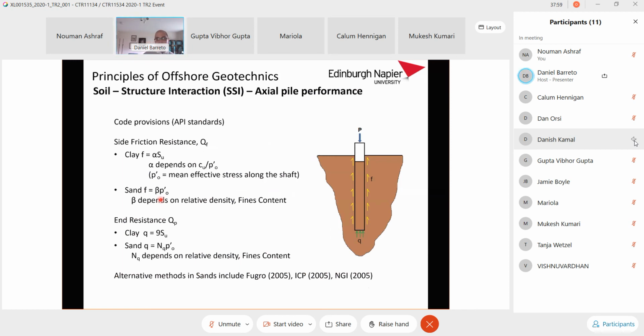That extension, what it means is that for offshore piles, you still will do calculations of total pile capacity being the sum of base capacity at the bottom of the pile and shaft capacity along the perimeter of the piles that you design. But while that will depend on things like the alpha coefficient and the undrained shear strength and bearing capacity terms at the base, as we did in previous courses.